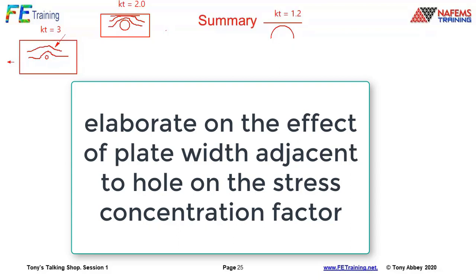So it's actually like two things going on. It's like a double-edged sword. Your stress concentration factor goes down, the example we have at the right, but the nominal stress goes up. So it's again a very interesting kind of effect there. And it aligns to the previous question on can we actually put holes and features in a sympathetic way? Yes, we can. So there's all sorts of interesting things we can do to juggle to try and get that stress flow to be an optimum.